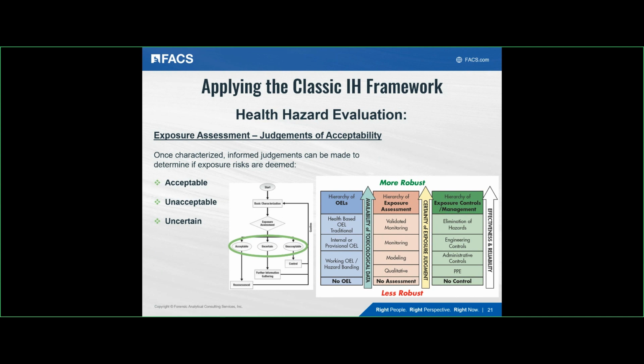An unacceptable judgment is one where the average exposure, TWA, or the upper extremes of the exposure peaks were high enough to present an unacceptable risk, i.e. the exposure exceeds the OEL. Unacceptable exposures are to be put on a list for control, and that list should be prioritized such that the higher exposures to higher toxicity agents should be controlled first.